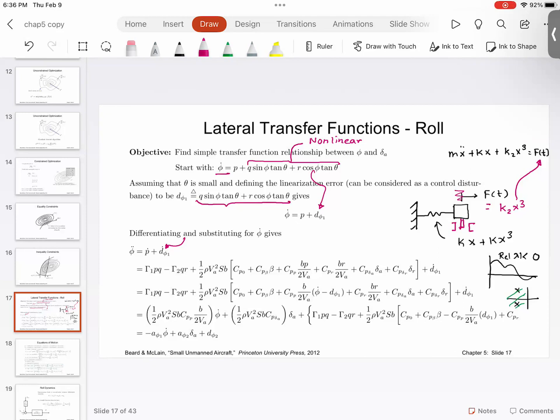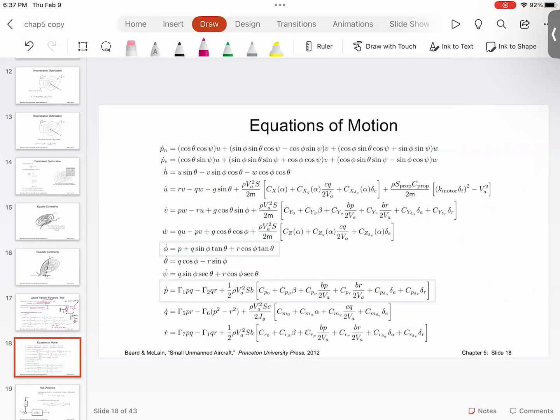Do you remember what a transfer function is? Ratio of output divided by input in a Laplace transform. And for transfer function, you should remember, if you have x dot, it becomes sx. If you have xt, it becomes xs. If you have x double dot, it becomes s square x of s. Right? So now what you need to do is, you need to see what is an output, what is the input, take transfer function, and trust me, your life has just become a lot more easier. So that exactly is what needs to happen. Take this equation, take the derivative, substitute this in here and then simplify so that at the end, the final equation, what you get is linear. Are you with me so far?